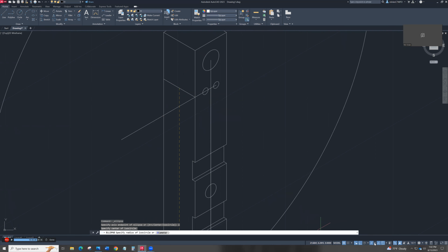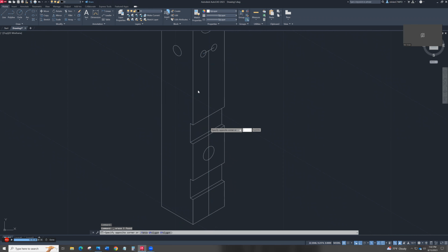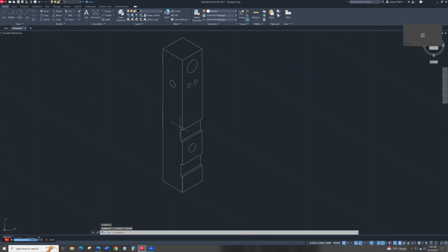So I need to change my isoplane again, and this one's going to be on the left. It's going to be this way. That is a 1032, which I believe is 0.190 diameter. Okay, now I didn't push diameter. Key for diameter. 0.190. Okay. And delete whatever lines I don't want anymore. This guy, him, and him. Okay? And there is my part.